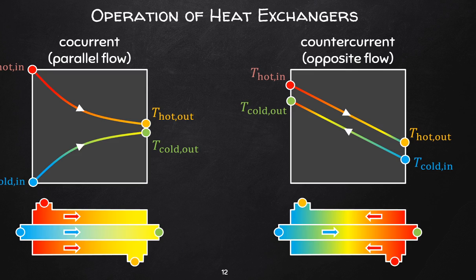Now why then would you want to use co-current heat transfer? In some applications this is very necessary, such as with a flooded evaporator that uses a very large temperature gradient at the inlet side to drive the boiling process more easily in the beginning.